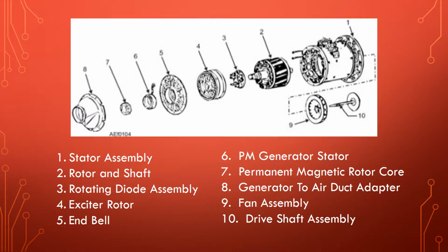Most modern naval aircraft utilize brushless generators for voltage generation. The brushless generator is a salient 8-pole, 6,000 RPM AC generator. It has a 12-pole AC exciter and a 3-phase half-wave diode rectifier rotating with the exciter armature and main generator field assembly.